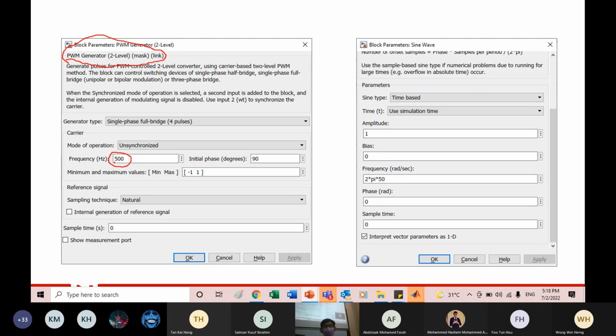Our voice is roughly around 1 kilohertz. But you see the frequency used to carry it is megahertz, so many times higher. That's why FM radio has the most clear stereo quality. But AM radio is in kilohertz. It's very much lower, but still higher than our voice and the music we hear. So it's able to transmit, but the quality is not that clear. So that is the reason.